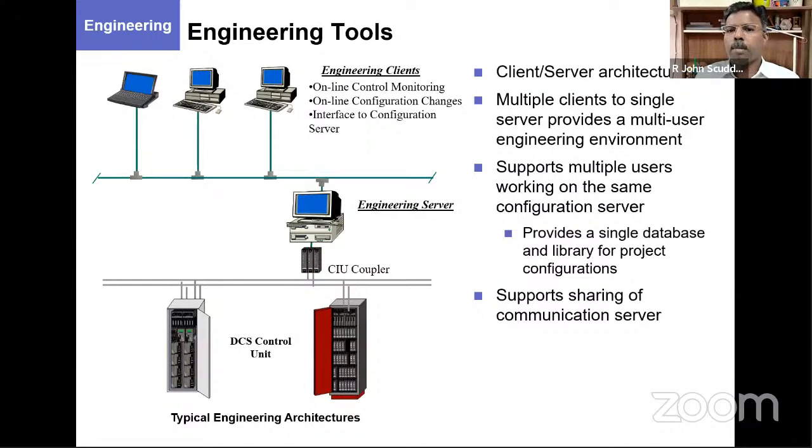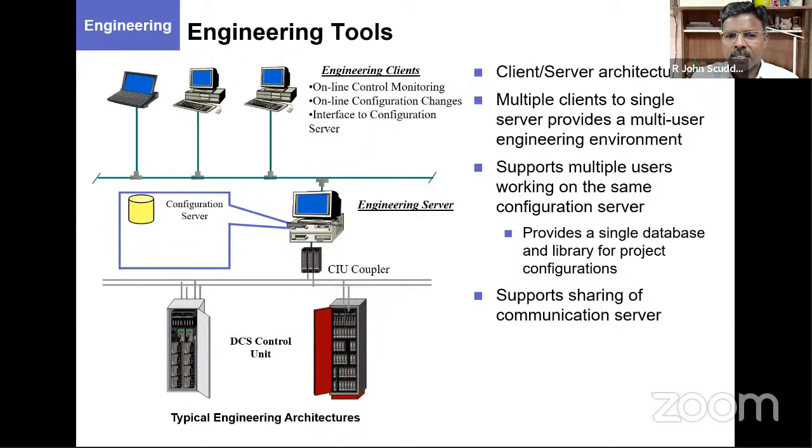So in case there is any problem, say one pump is starting and another pump's current is showing, they will immediately call you and say, "Arey, you have given a pump, and when we are starting this pump, the current of the other pump is only increasing." So then you need to analyze whether you have made any logical mistake in the engineering server, and maybe you may have to replace those things. Hope I'm able to practically put it to you. I'm sure it's not easy for you to visualize everything, but we will try to understand.